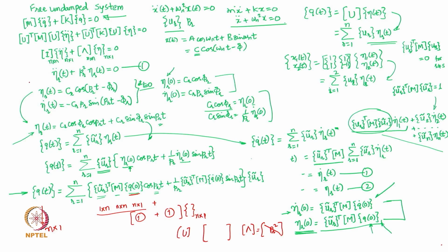Because we have a very standard way of finding the response for a simple single degree of freedom equation of motion, and using those equations and that process, we could do that because we were able to decouple all our coupled governing equations of motion through the modal transformation, right. We got all the physical coordinates transformed to a principal coordinate, which caused all this decoupling, and so things are very simple. Now you can realize, once you get the hang of the basics of a single degree of freedom system,